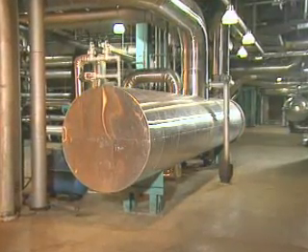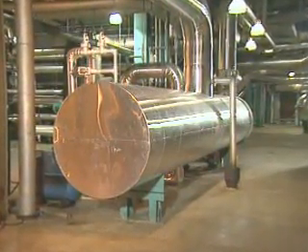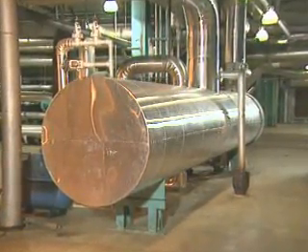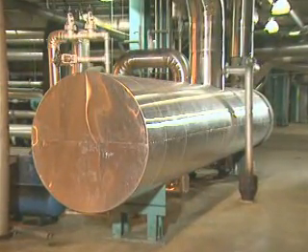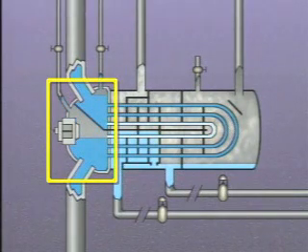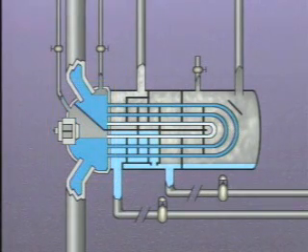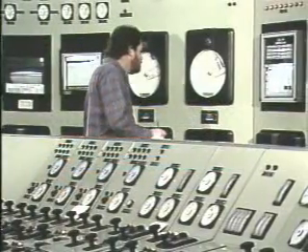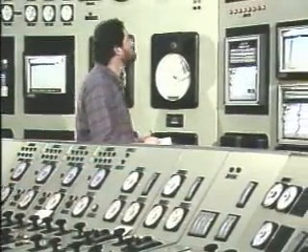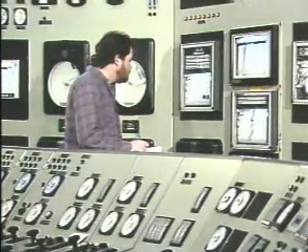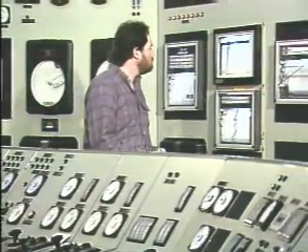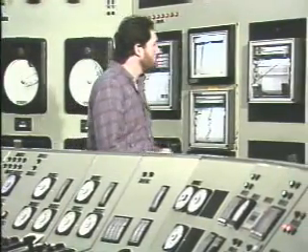Improper venting of a heater can cause air binding. When this occurs, air is trapped in either the tube side or the shell side of the heater. Air that collects in the water boxes on the tube side of the heater can restrict the flow of water through some of the tubes. The restricted flow causes the velocity of the feedwater to increase because the same amount of water must go through fewer tubes. The increased feedwater velocity can cause the terminal temperature difference, or TTD, to increase, although the drain cooler approach, or DCA, remains normal.